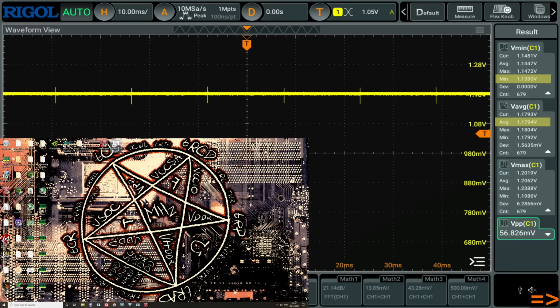So the thing is, Mode 1 LLC is just terrible for voltage regulation. That's really not surprising. There's no V-droop. We're literally seeing undershoot under load that is worse than what we get at idle, both in terms of idle average voltage and undershoot at idle. So yeah, Mode 1 is unusable, which is really unsurprising.